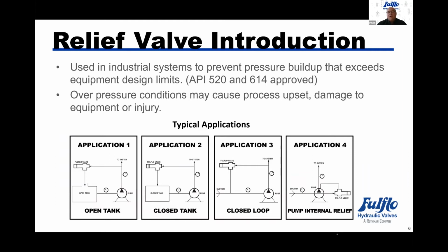The valve does work off of differential pressures. Typical application number 3, the valve's pumping out of a pump, which could be a centrifugal pump or a positive displacement gear pump, where it's pumping back into the suction side, the inlet of the pump. Application number 4, it's just circulating within. A lot of times you find these for PD pumps, positive displacement.